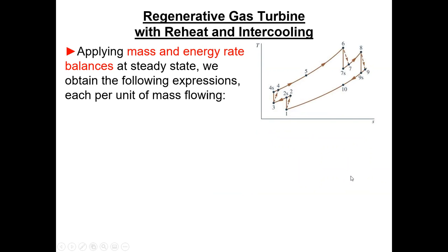If now we want to show the entropy increases, then this is what the cycle looks like on the TS diagram. So what 1 was into the first stage of compression. So instead of straight up, you just got an entropy increase you have to deal with. And then this was intercooling, and then we compress again. So instead of straight up, you're at 4. And then the regenerator takes us to 5.